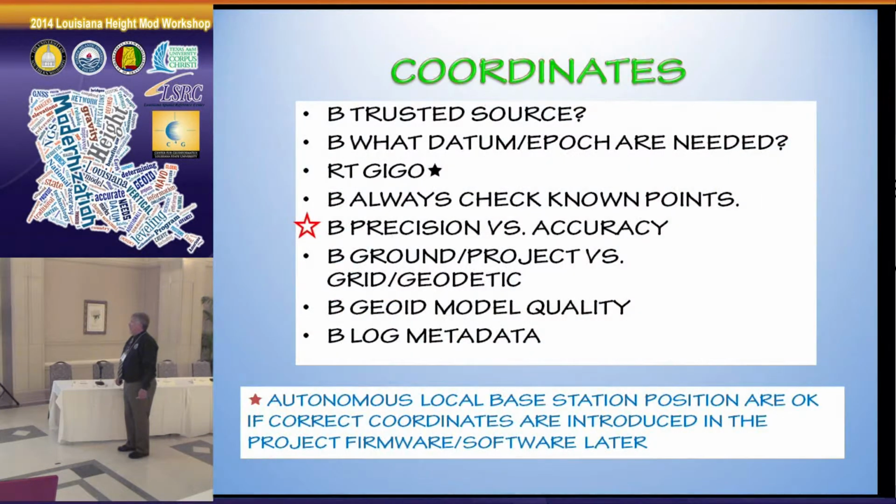I think we talked about that. If you can do autonomous positioning with real time, if you enter in the right coordinate for the base station later. So if you're out at a site and you say, oh man, I forgot that data sheet. I don't have it. Okay, well just set your point up, do an autonomous position, do your real-time positioning, then